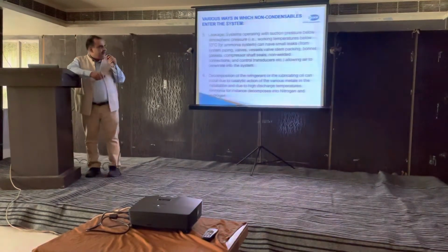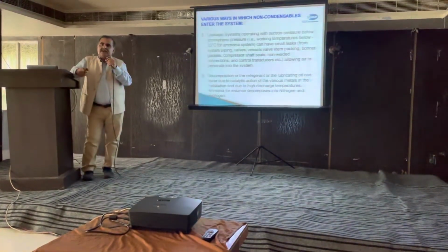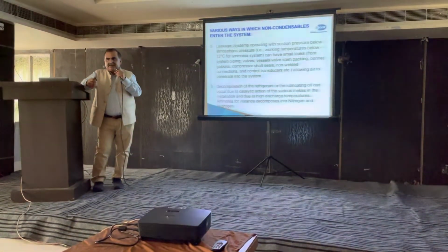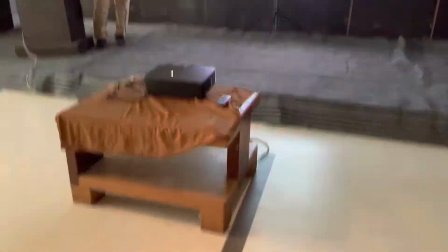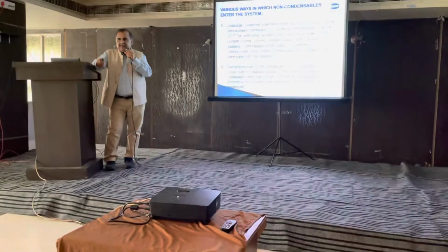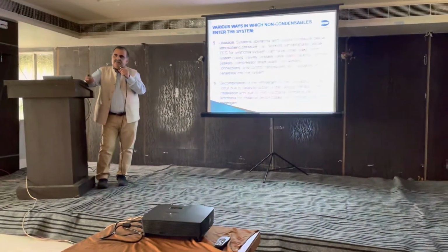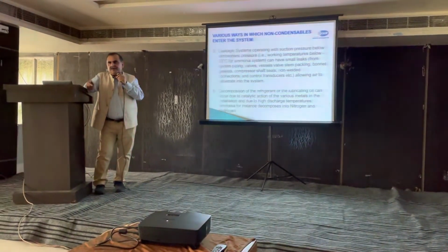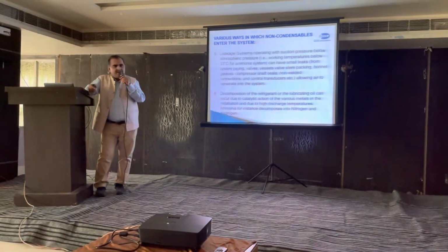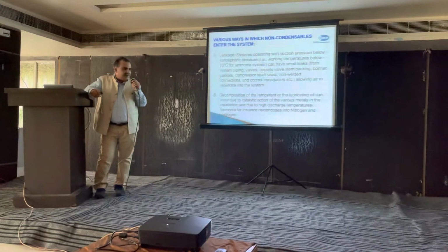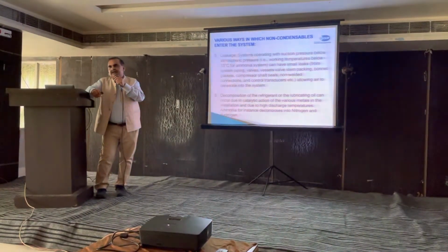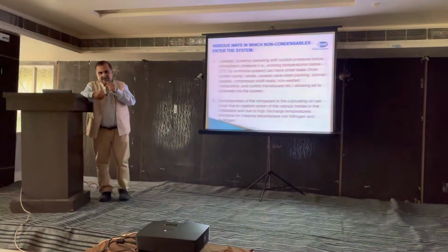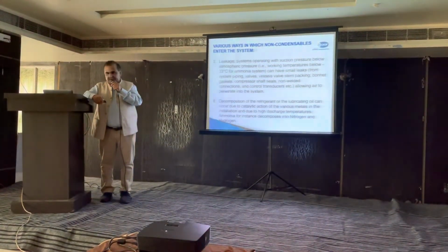And then, as I told you, when air starts increasing in our plant, our temperature increases and discharge pressure increases. This also affects the oil in the system. If this oil, whether synthetic or mineral, which is again mostly made from hydrocarbons, breaks down, those hydrocarbons also become part of our non-condensable gases or air. And they further increase the temperature and pressure of the condenser or discharge of the compressor.